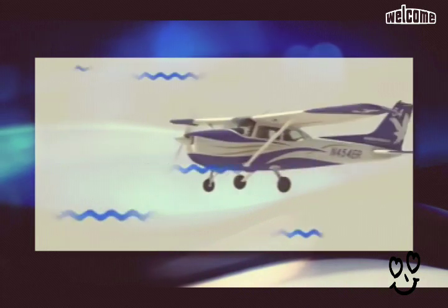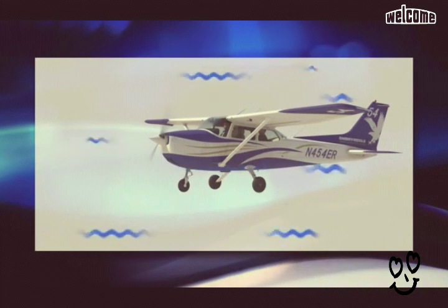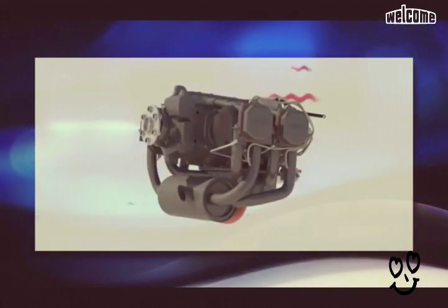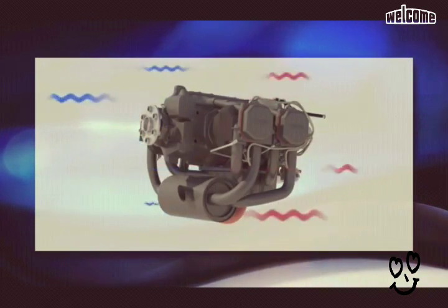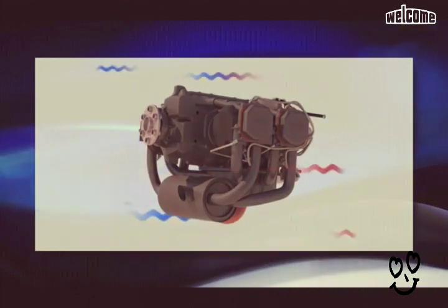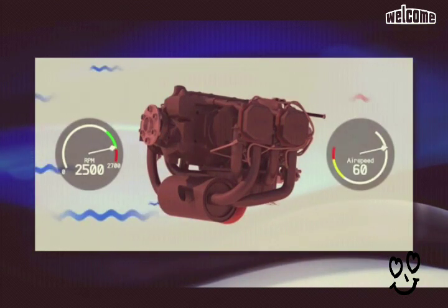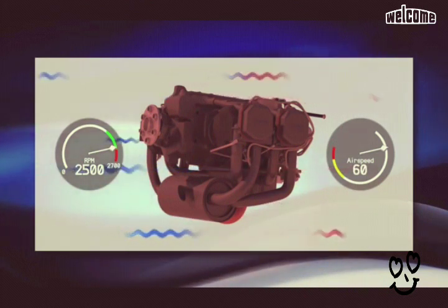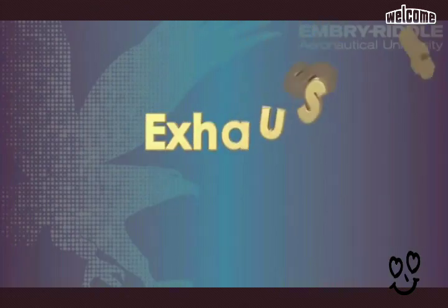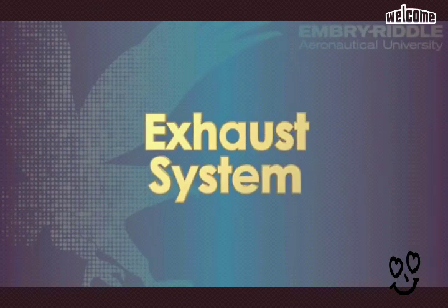However, we also use air to cool our engines. As the airplane flies through the air, outside air flows through inlets usually found on the front of the airplane like the Cessna 172. This outside air is colder than the engine, so as the air flows over the engine, it cools it in the same manner that the oil cools the engine. This method of cooling can be severely restricted, however. When the airplane is running at high power and at very low speed, such as when climbing, airflow is minimized, causing higher temperatures.